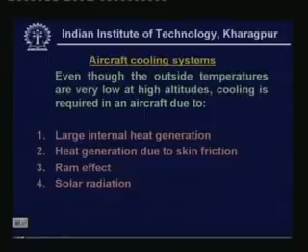This is not the only reason. You also require cooling because there will be heat generation due to skin friction. Typically aircraft will be moving at very high speed. So, when it is moving at very high speed in air, there will be large relative velocity. So, the boundary layers will develop on the surface. And since air has a finite viscosity, as you have seen in the earlier classes, there will be frictional losses, and because of the skin friction temperature rises. The temperature of the outside body will be higher because of the skin friction. So, there will be actually heat transfer from the surface of the body to the interior because of the skin friction. So, this is the second reason why you need a cooling system.